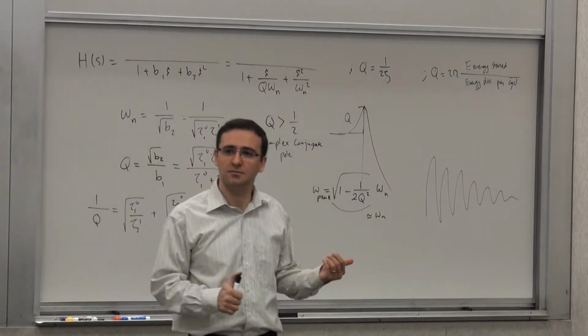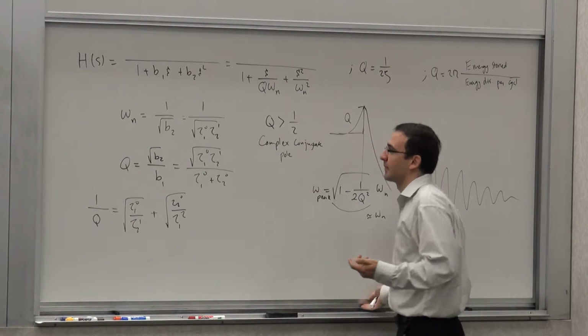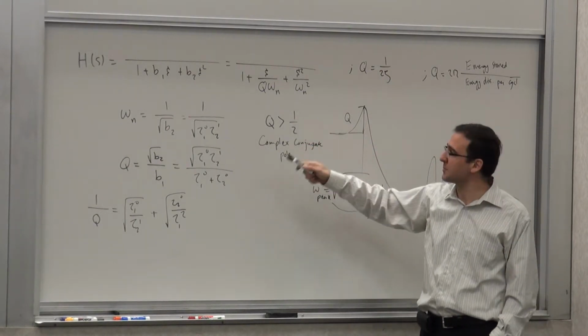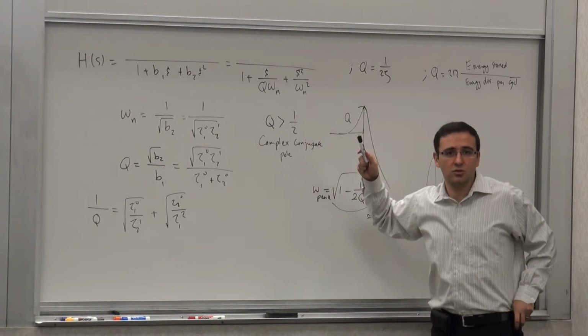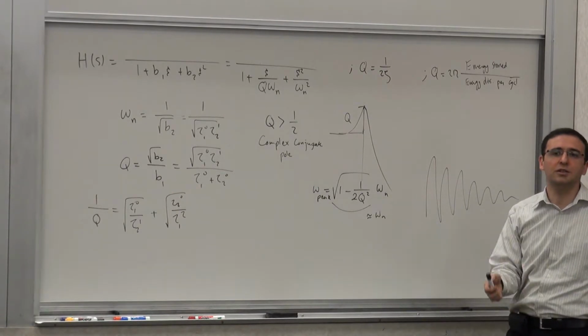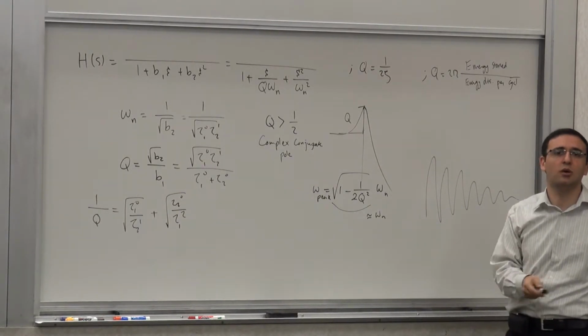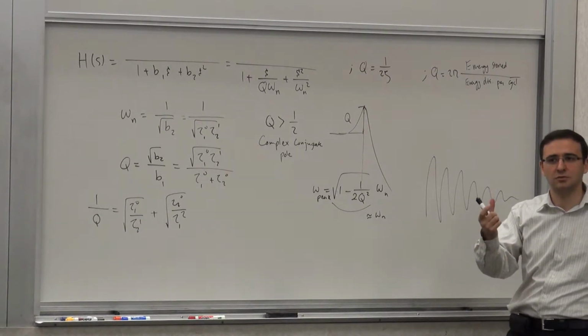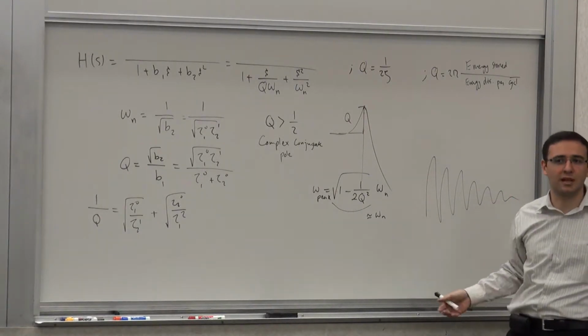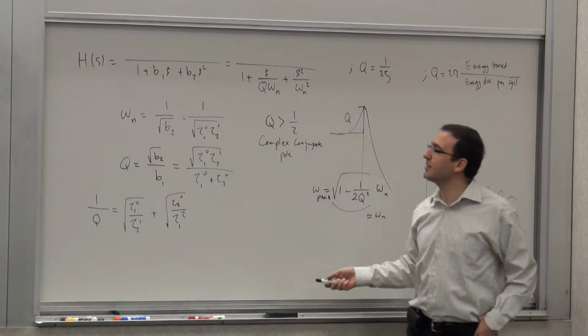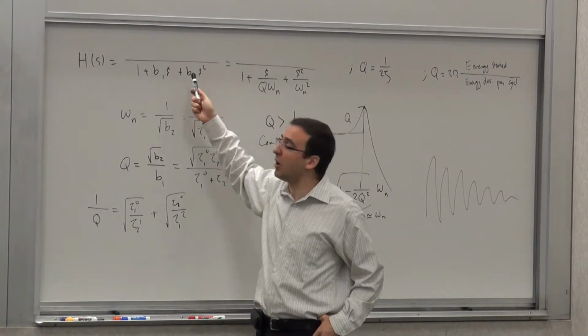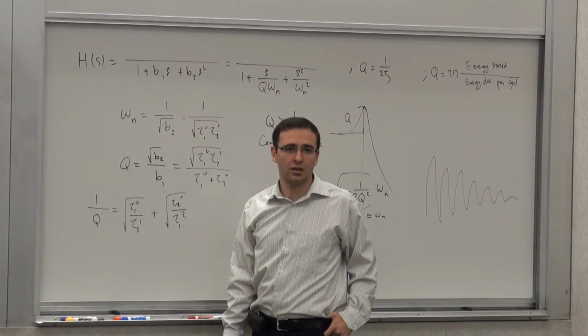Any other questions on this? Well, this is actually very useful in second order systems, or higher order systems too. So you can use it as an approximation. All you need to do is determine V1 and V2 and calculate the square root of V2 over V1, and that gives you a Q. That tells you if your system is underdamped or overdamped.